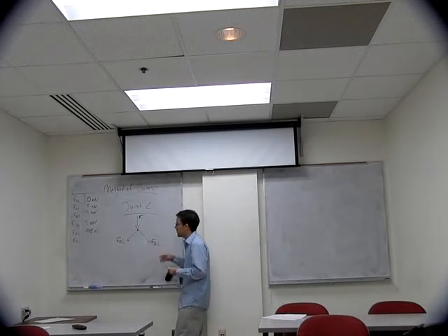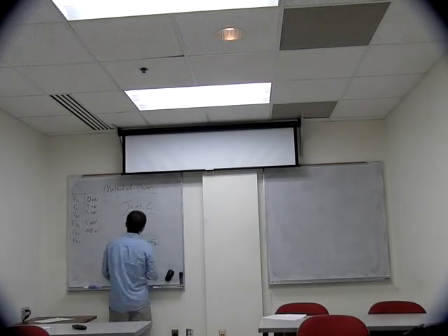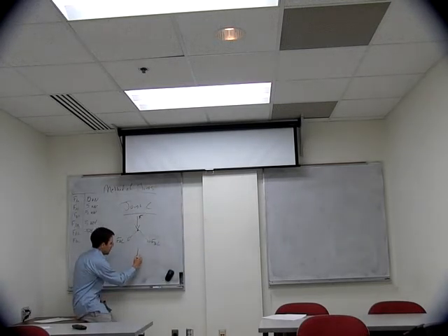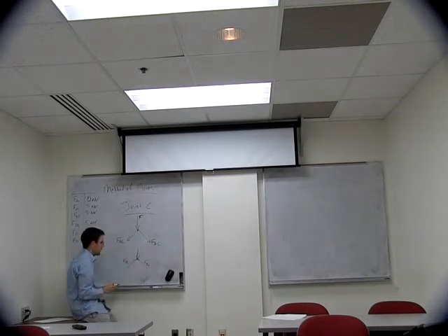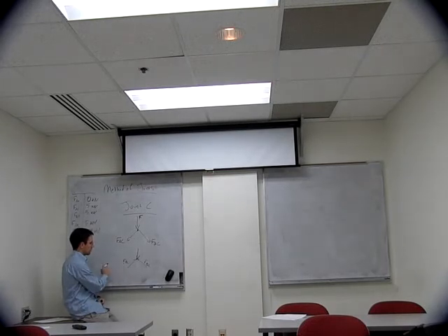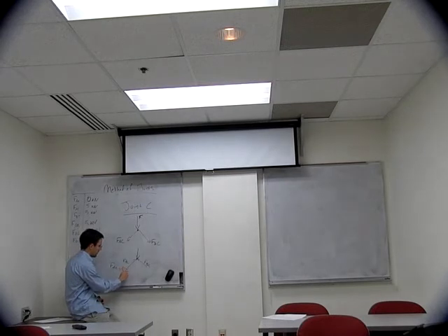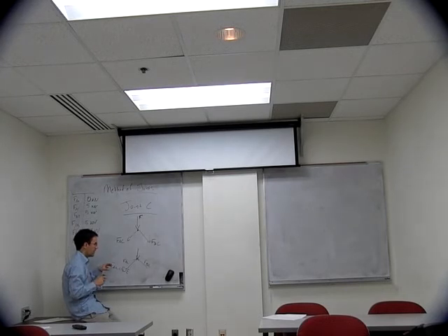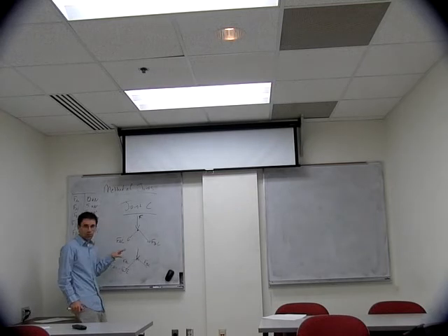One thing you can potentially do is actually go back and redraw the entire system. So you could draw joint C like this. You still have your downward applied force, and you can reverse the direction of FAC and FBC. But here, what you have to do is relabel FAC as being positive. So it'd be 5 times the square root of 2 instead of negative. And this is fairly simple for this example that we're doing now.